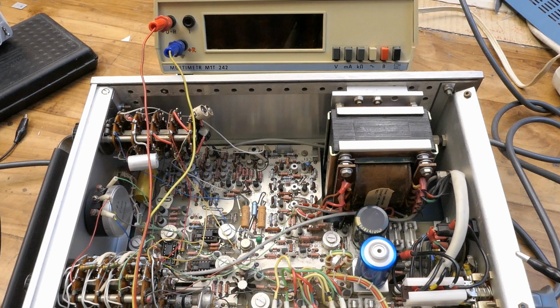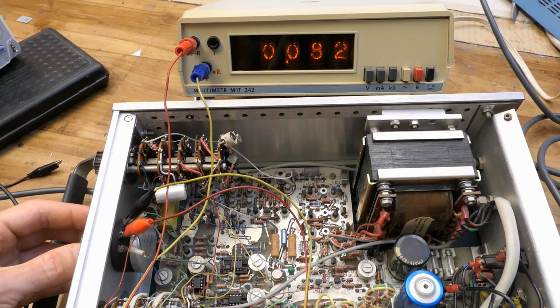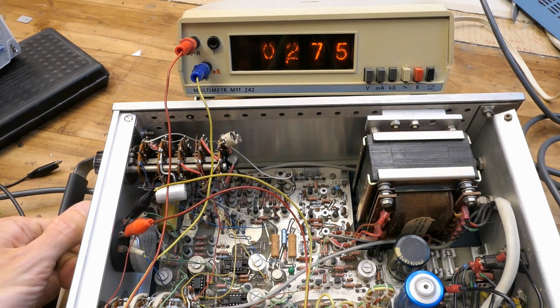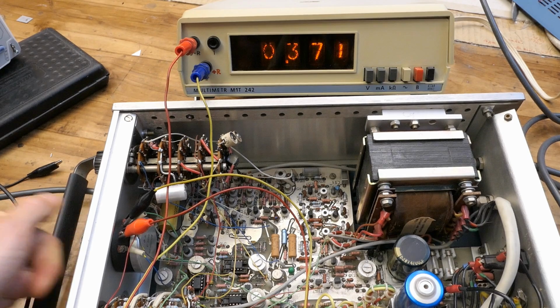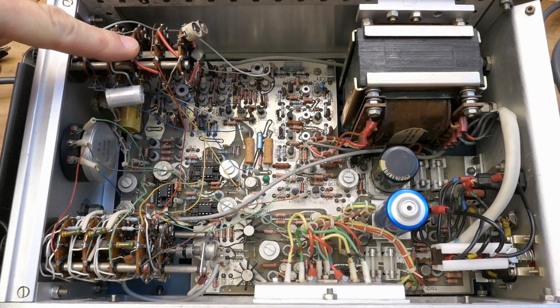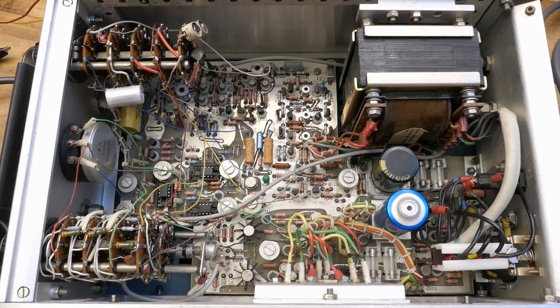If the supply voltage was wrong or non-symmetrical, if one of the rails was off, it could cause this problem, but it doesn't seem to be the case. And this potentiometer seems to be right. The slider is making contact in all positions, it seems. This seems good. Because the problem is frequency independent, it doesn't depend on the position of this decadic switch. It can't be any capacitor or inductor. It has to be something like a resistor or some semiconductor like a transistor, chip or diode.